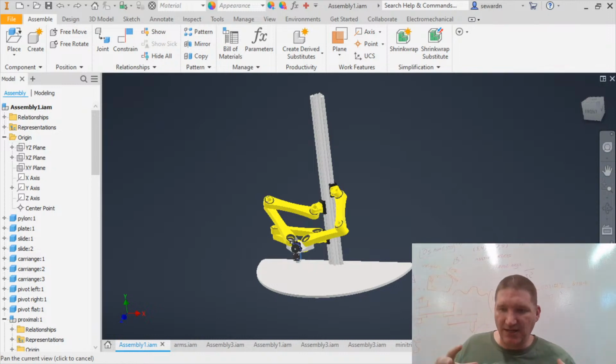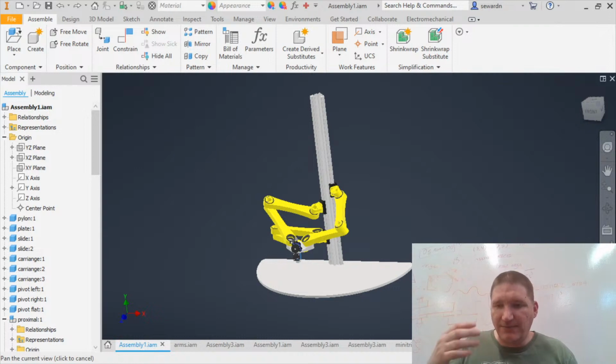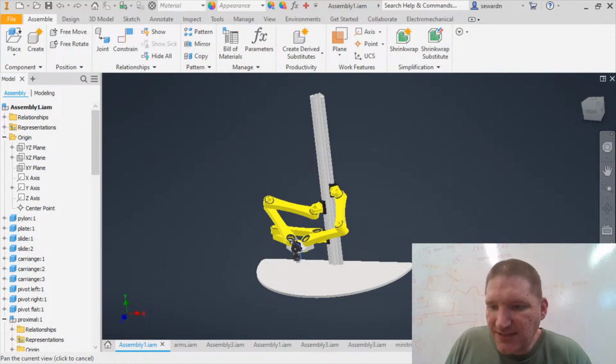Pretty much any robotic machine designed over a certain size, you'll transition away from smooth rods to rails that mount to some rigid frame. It's very easy, like that BH cubed formula I'm talking about. It's easy to add the mass, so you don't want your precision component to have to be that big just to get the rigidity that you want. So you have a smaller precision component and you mount it to a large massive thing. So anyways, hopefully that answers that.